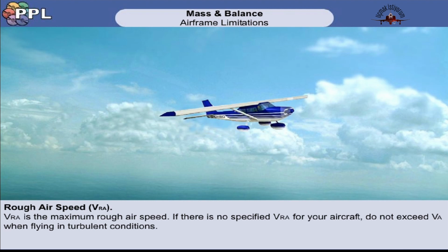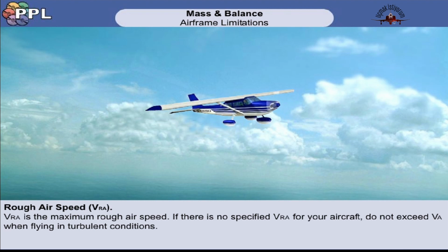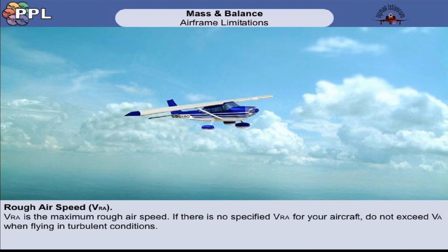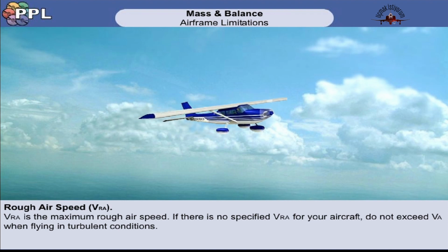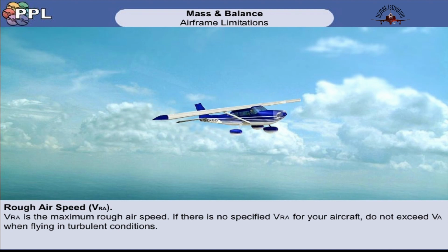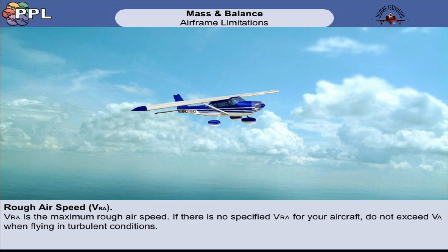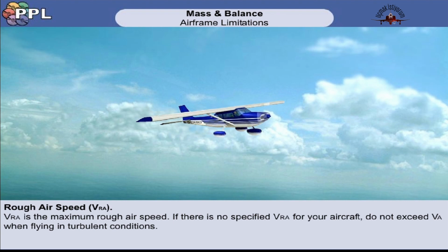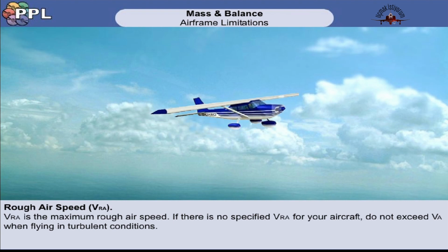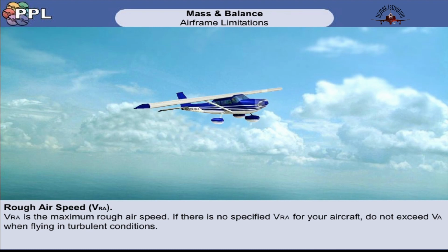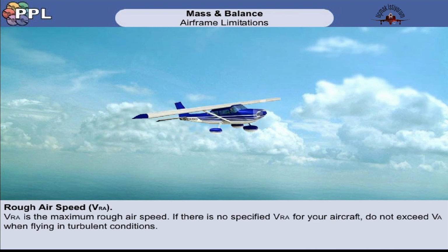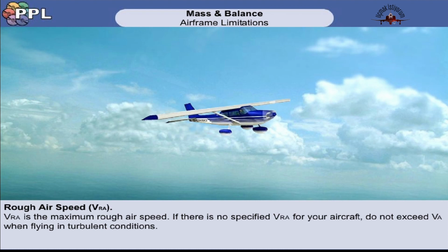Remember that these speeds are targets. The turbulent conditions will cause your indicated airspeed to fluctuate, and by chasing a speed, you may overstress the aircraft. Remember also that the turbulence may cause your altitude to fluctuate wildly. Don't chase it. As long as you are in no danger of hitting the ground or other aircraft, allow the aircraft to ride the gusts.